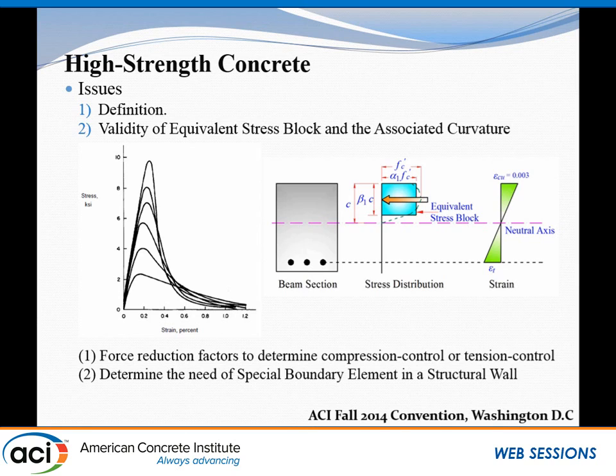Most of the previous researchers answered this question from the strength point of view. The curvature associated with the nominal moment strength has been overlooked. It should be reminded that the nominal moment strength was originally developed for the flexural strength and was not intended to evaluate the member deformation.